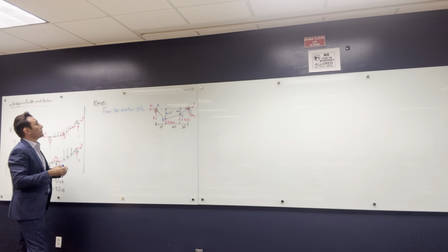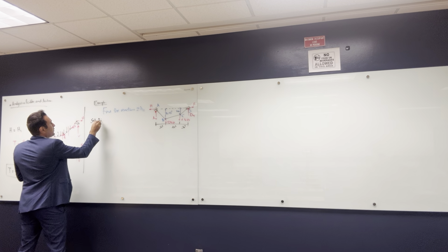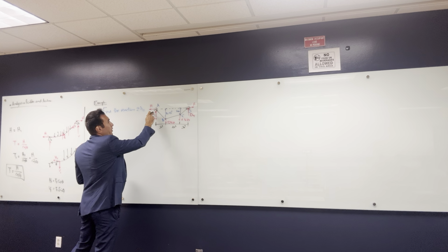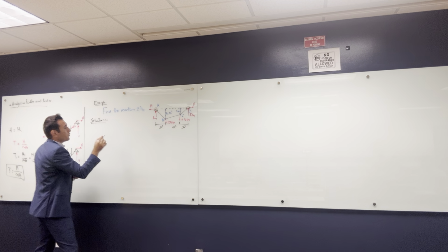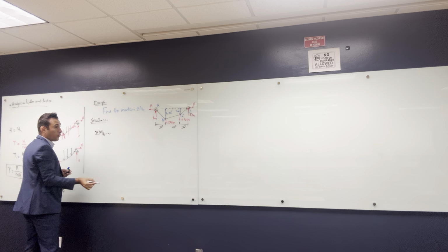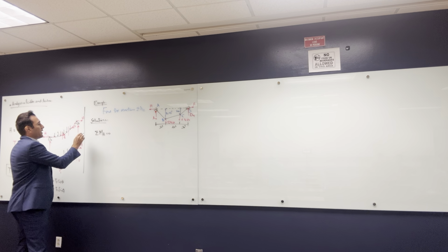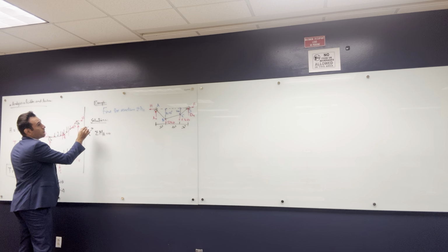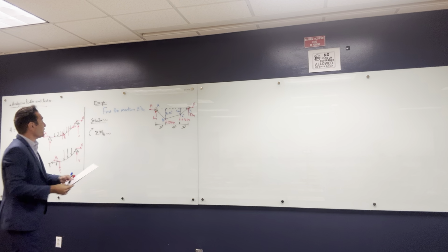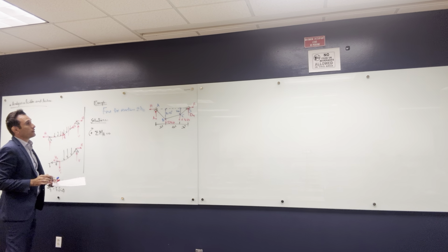Moment, right? Excellent. So I have the solution. You can start either the moment from the left or the moment from the right. So I can say the moment about A or the moment about D. So maybe I will say the sum of the moments about A should be equal to 0 if this is a static structure that doesn't move. And I can assume the positive direction maybe in the other way, because it's going to make it easier. You can assume it in any way. Actually, assume in this direction, so we can have the same numbers.